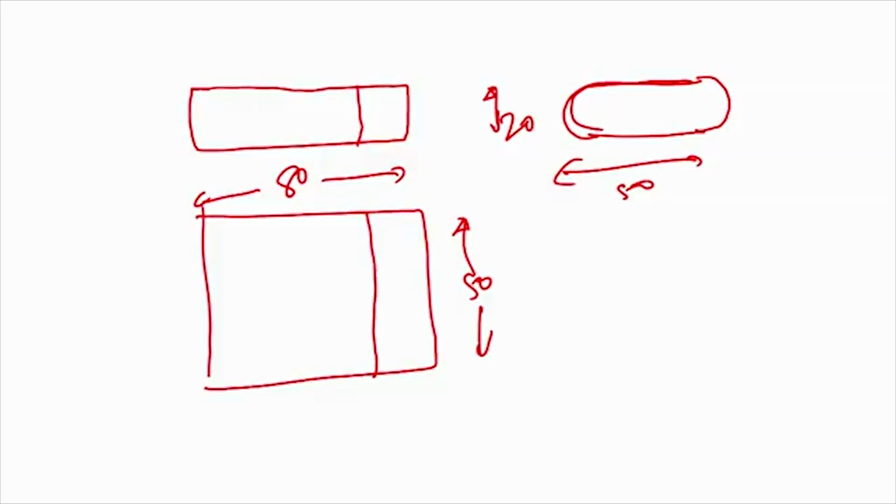Next comes how do I produce this radius. So I need to show here what this radius is. So I indicate here saying approximately it is 10 millimeters. It is fairly complete, because normally it is understood what it is, and further often people show the center line, sometimes they show the center distance, but it will be redundant if I put 10 here and 50, it will be redundant. So R is equal to 10, this is sufficient for me.